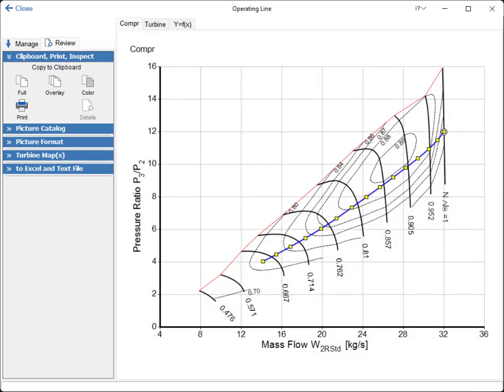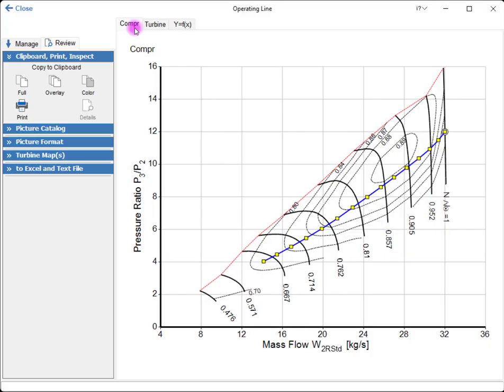As the reference value of the relative spool speed is the dictated design point condition, the speed line passing the design point has the value of 1. The values of the other speed lines are now scaled according to the changed scaling point value. Now let's draw the graph Specific Fuel Consumption over Net Thrust.